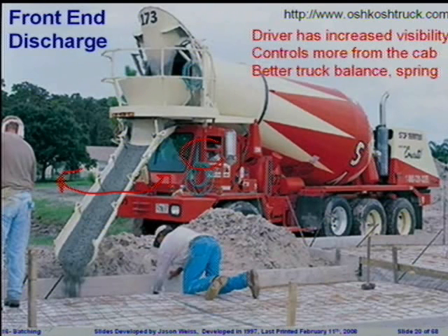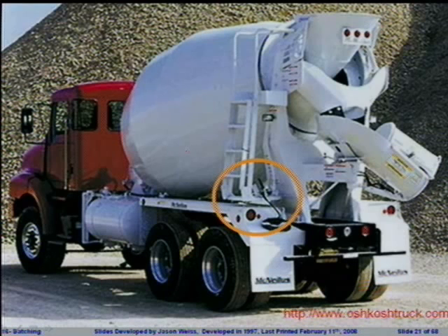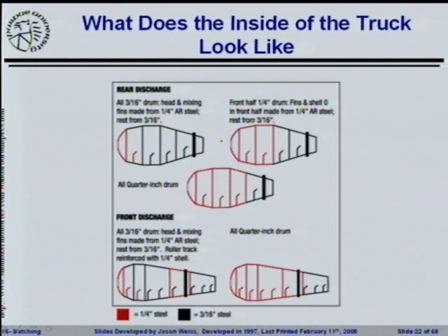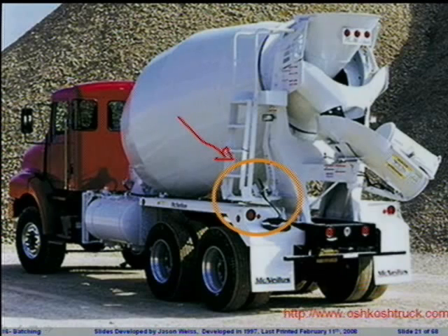And the whole time you were doing the measurements as graduate students, he was adding water to the back of the truck, which meant that you were measuring something that didn't have anything to do with what was in the back of the truck at the time. And I say this because I think it's important that you understand where water can and can't be added in the overall process. Back of the truck is typically where the business is going to take place for a rear discharge truck. Here you can see it's the exact same thing, only it's in the reverse order.